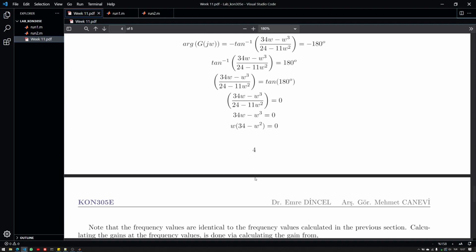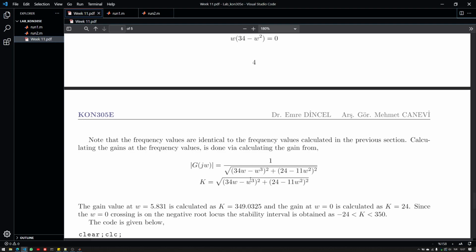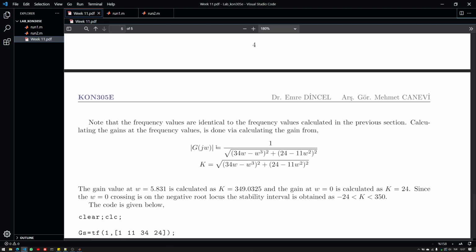Yes, so you can see that there are again two omega values. The square root of 34 should be familiar. And if you plug it in, again, it is interesting to note that we have the gain condition of the root locus, because 1 divided by this gives us basically the same effect, but you can see 1 divided by j omega gives us the distance. So if we plug in 0, we get the corresponding gain value. If we plug in square root 34, then this vanishes, and this helps us out in determining the values.